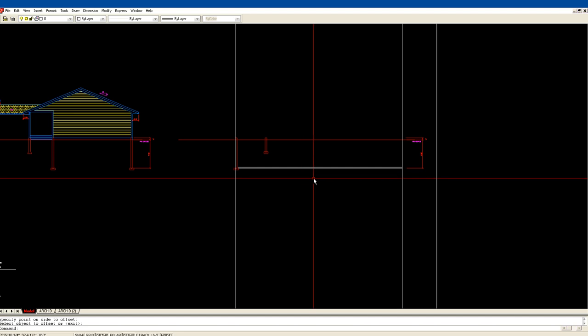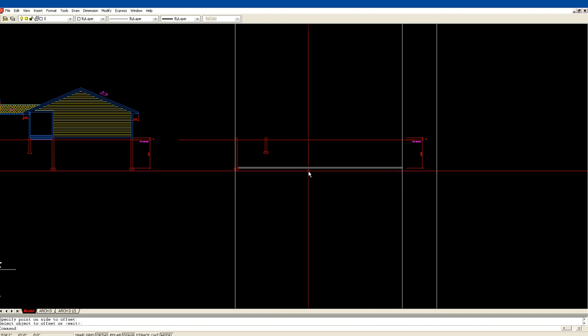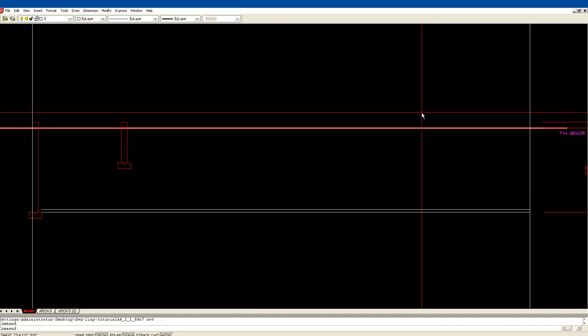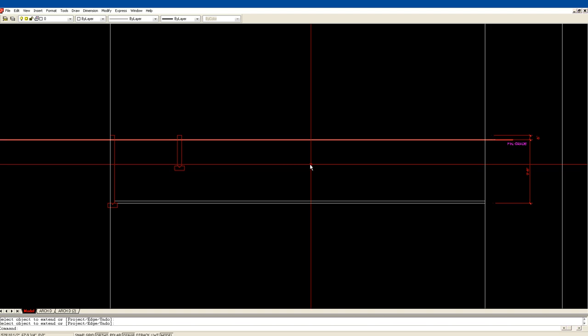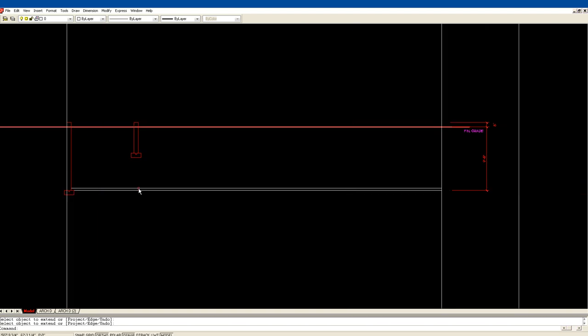Down here, there's no frost going to attack this basement slab. It can be 3 inches. I'm just going to extend it right to the inside of that wall. So we want one level for our basement. We are out deep, but he wants to walk out this end of the house underneath the deck. So here all we have to do is have concrete 4 feet below. In this area it's 4 feet below frost, or 4 feet below the surface.